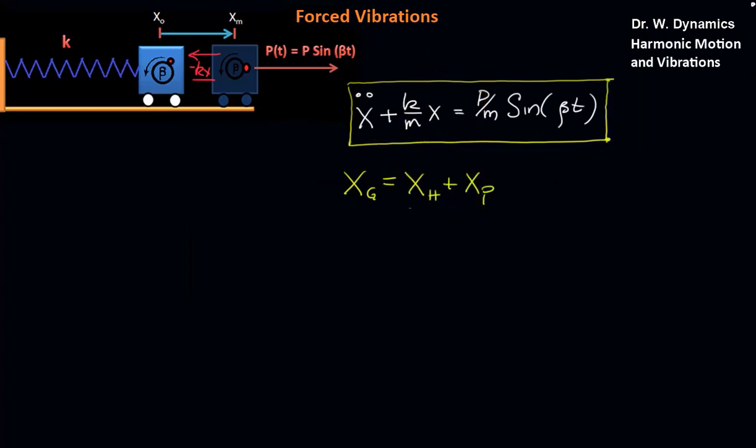We already know our homogeneous solution was a sine of omega t plus phi, where that's our natural frequency from this term right here. We know that that's omega squared. And now we can look for the particular solution. The particular solution needs to generate this function, so we'll assume that it takes on the form of our sine function over here, since we have to generate that.